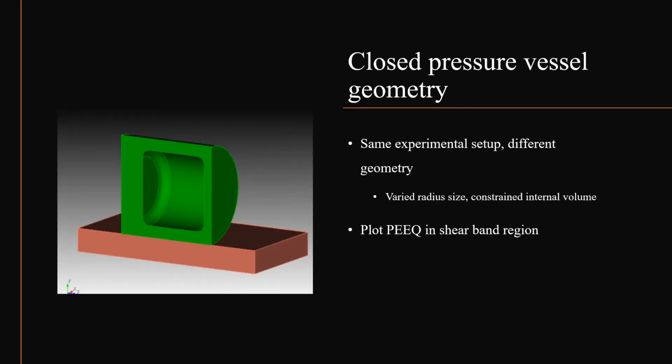Now that I had determined the locations of high strain in the simplified model, I applied the same setup to a more realistic pressure vessel model that was completely enclosed. I found that the strain results and locations were similar to the results found in the previous simplified geometry.